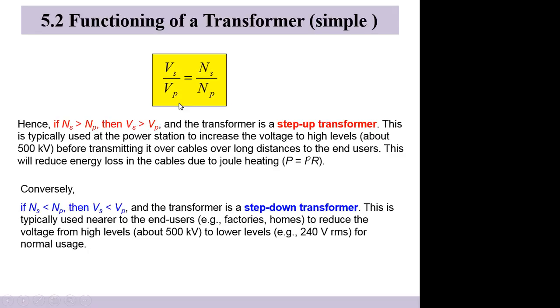That means in the exam, I can tell you the turns ratio is 5,000. You need to know that it means that the secondary side has 5,000 turns to 1 turn on the left-hand side, on the primary side. Because I got students who saw the words turns ratio and cannot change it to this ratio. You thought it's 5,000 on the primary side and 1,000 on the secondary side, and wrong. So that's something that's not in the textbook. I mean, not explicitly stated.